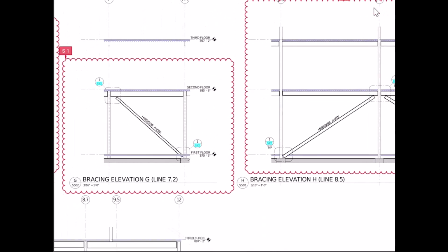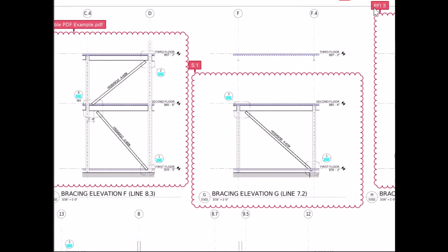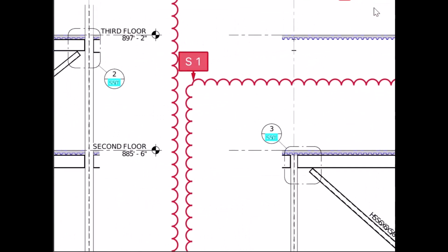And again, I always recommend submittals, your finishes. I worked on a fitness center that had 300 plus different finishes and like 70 different types of wall coverings. I don't expect anyone to memorize every single one of those. However, if you have a finish schedule, you can separate out, or have your project engineer or whomever separate out those finishes on the approved submittal, put them in the documents folder on Procore, and just link each of them.